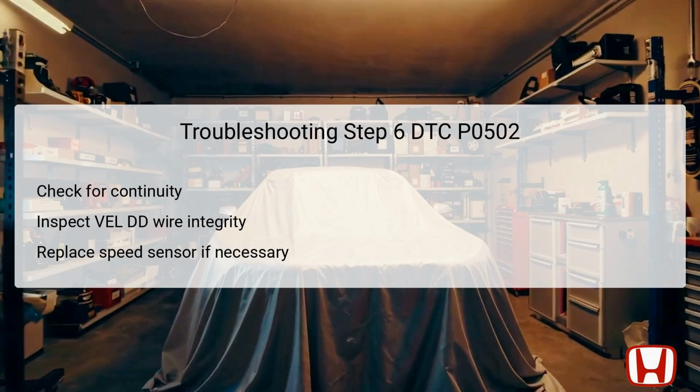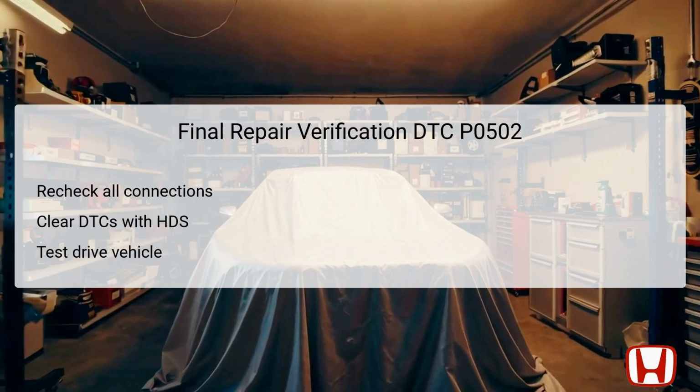If continuity exists, but the DTC persists, it may indicate that the CVT speed sensor itself is faulty and should be replaced. Conversely, if the continuity test fails, it suggests an open wire that needs to be repaired to restore the circuit's functionality. After completing the diagnostic and repair procedures, it is crucial to conduct a final verification to ensure everything is functioning correctly.